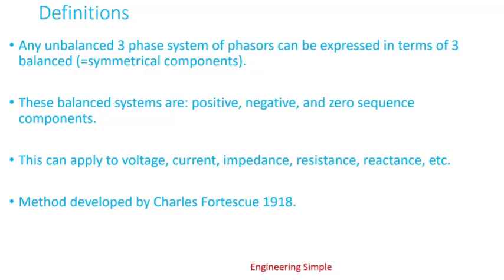So basically, with symmetrical components there is an assumption here: assuming that the power system is balanced from generation to the point of imbalance or the point of fault. So wherever you have imbalance, like single phase loading, or you have fault currents like line to ground, line to line, or line to ground faults, that can cause the system not to be symmetrical.